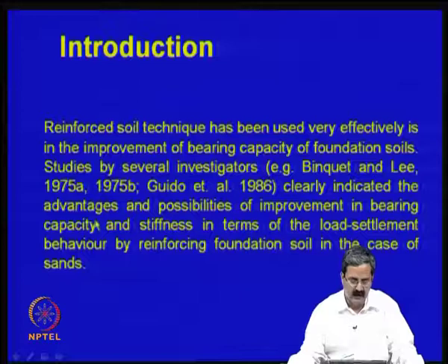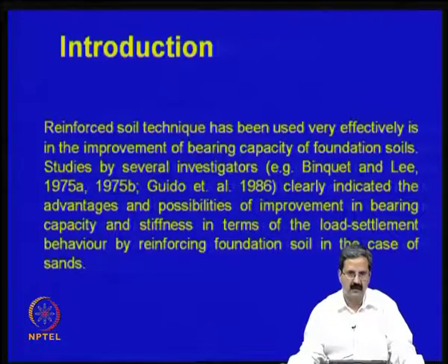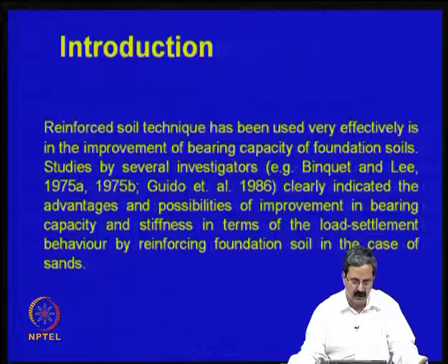They were clearly able to bring out the advantages and possibilities of the improvement of bearing capacity and stiffness in terms of the load displacement behavior or load settlement behavior, because we try to do a plate load test. A simple case is that you do a plate load test on a typical soil and then put the reinforcement and again do a plate load test, to see how it can improve. So, in this class today, we would be talking about bearing capacity improvement in the case of sands.